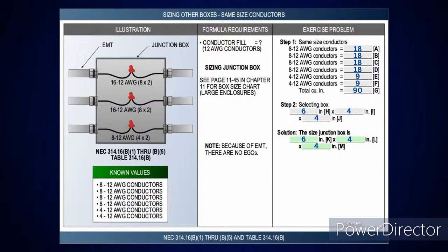I want to bring up something real quick, James, and I think it's funny how this illustration helps me talk about this. We've come into this new myth that a lot of people talk about, where they're saying that you don't have 6 inches of free conductor in that illustration. But running a pigtail with that splice in there is actually compliant for your 6 inches of free conductor.